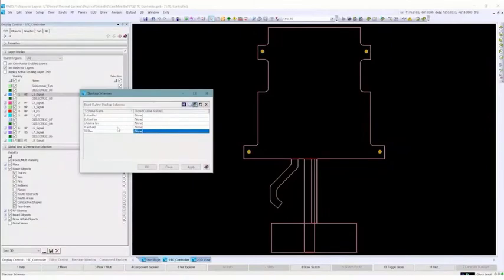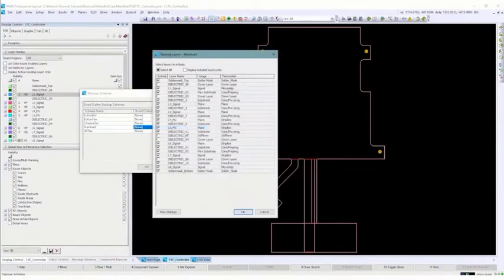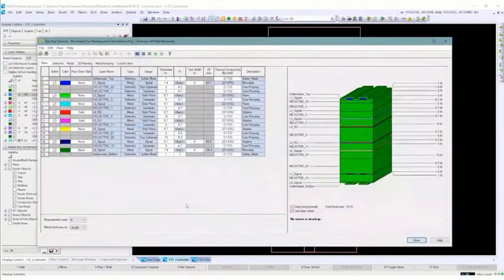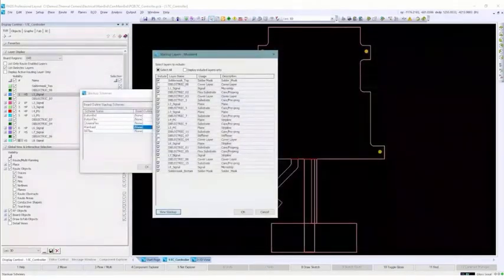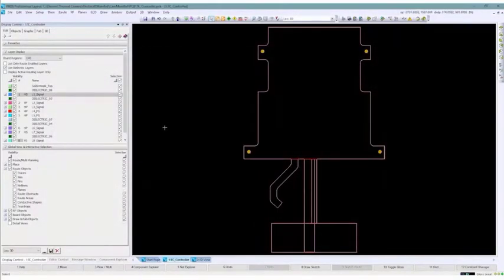And then we'll review some of the other ones like the main board. I've already gone ahead and created these. View the stack up again as normal. You can adjust your layer thickness parameters as needed. So we've done one of the most important parts in designing a rigid flex board, and that is defining our stack up region or Stackups that we'll use in the different regions of our board.